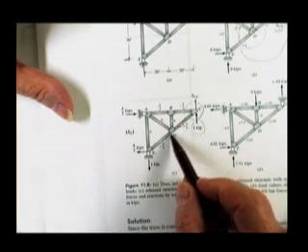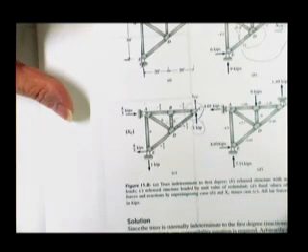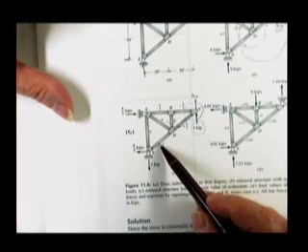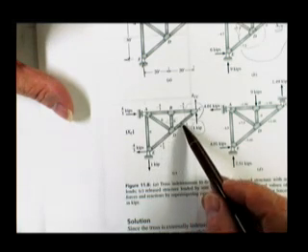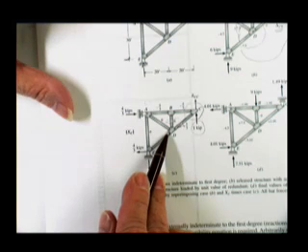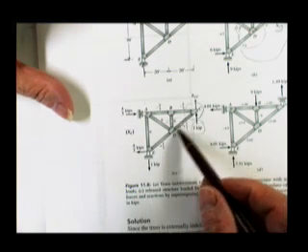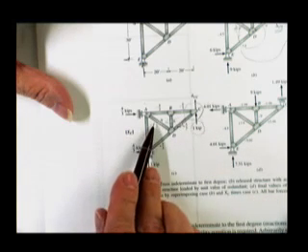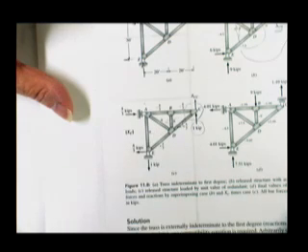He comes down to this. He, in effect, takes that member out because it has no force in it. He has a pair of collinear members, with somebody coming in from the side trying to say, can I push, can I push, can I push? The answer is always no. Anytime you have a pair of parallel members with only one member coming in, the force in that has to be 0. It's a 0 force member.